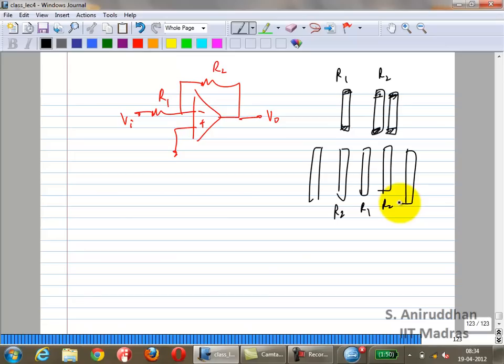You have to worry about the capacitance now. Okay? And of course the area occupied, because if you talk about 100 ohms, 1 kilo ohm, not a problem. If you're talking about 100 kilo ohms, becomes a big problem. And same thing for the capacitors, not a lot of difference.